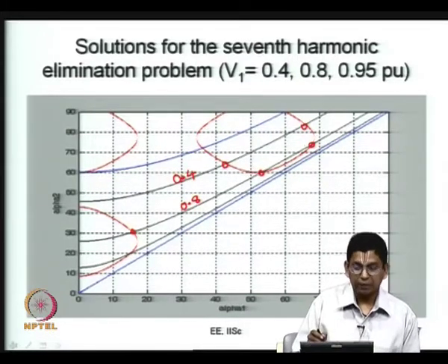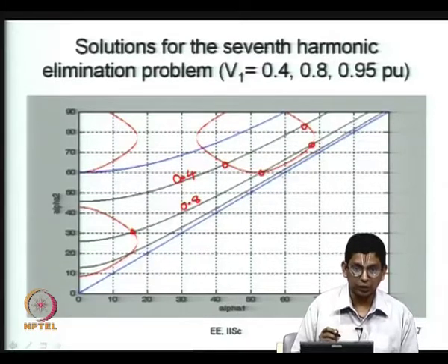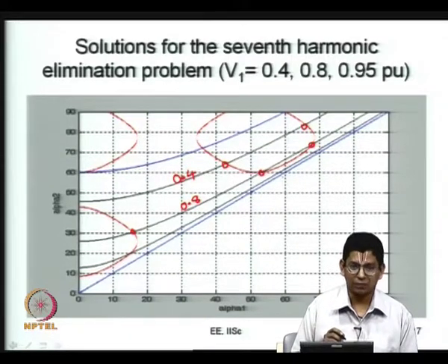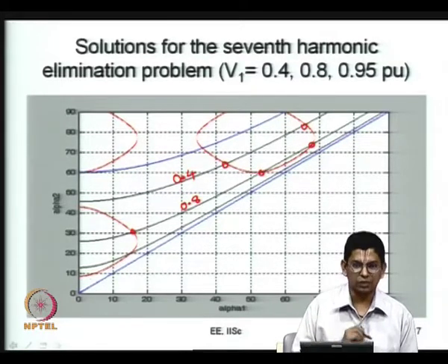So, one way, as I said, you can look at what the 5th harmonic is at those points. There are 3 points available, x, y, z, and you can see at which of the points V phi is the lowest and you can choose. Or you can also look at certain other criteria. As I will talk about a little later, you can also look at pulsating torque, that is also a factor. There are other issues that you can consider and choose one of these 3 points.